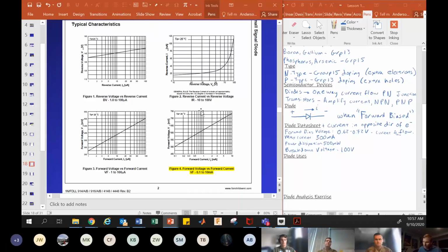So here, this is interesting. Look at this plot on the lower right corner. This is current versus voltage. So it's like the inverse of what we were showing before. But if this were a resistor, you would expect that as you increase the voltage, you increase the current, and it's a linear relationship, right? Now, why is this a straight line? Because I told you that a diode is not a linear relationship between voltage and current.